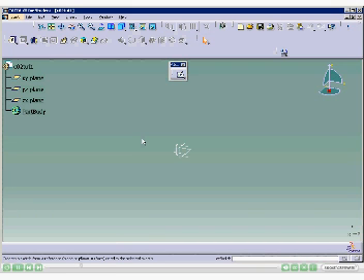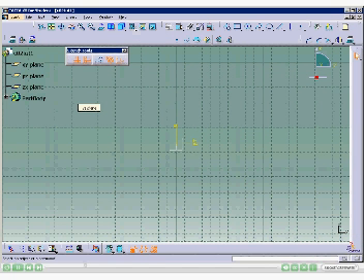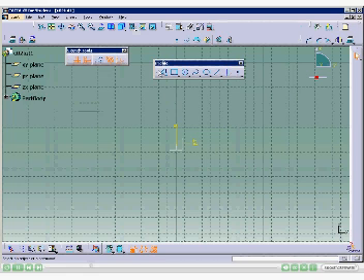To invoke the Sketcher Workbench, choose the Sketch button from the Sketcher toolbar, and then select the YZ plane as the sketching plane. The displayed screen is the Sketcher Workbench. Now you will draw the sketch in two sections: first, the outer loop, and second, the inside circle. First, take out the Profile toolbar. You should create the sketch symmetrically around the origin. This will reduce the time required to constrain and dimension it. The outer loop of the sketch can be drawn using the Line and Arc tools.